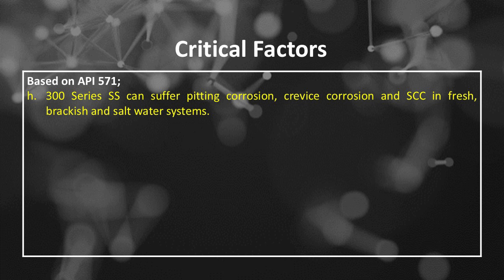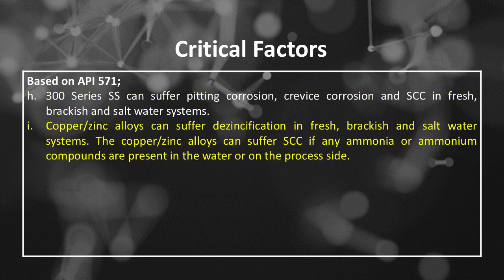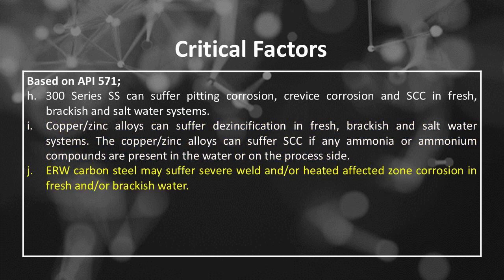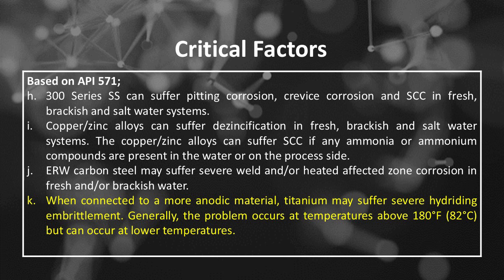Number H, 300 series SS can suffer pitting corrosion, crevice corrosion and SCC in fresh, brackish and salt water systems. Number I, copper or zinc alloys can suffer dezincification in fresh, brackish and salt water systems. The copper or zinc alloys can suffer SCC if any ammonia or ammonium compounds are present in the water or on the process side. Number J, ERW carbon steel may suffer severe weld and/or heat affected zone corrosion in fresh and/or brackish water.